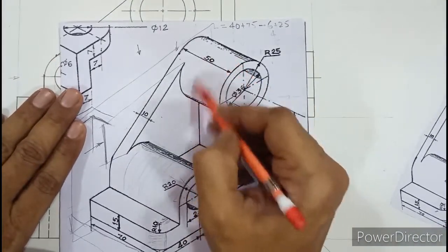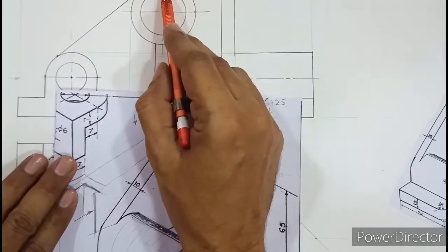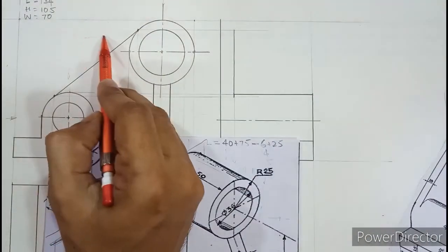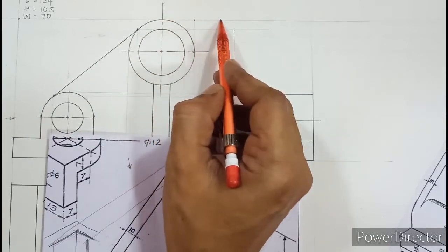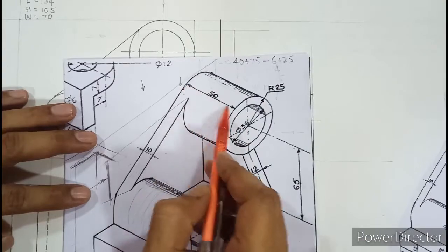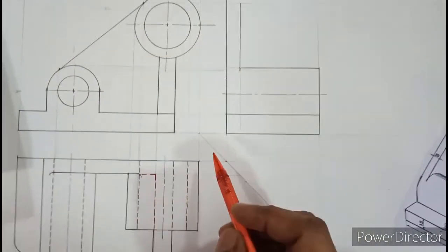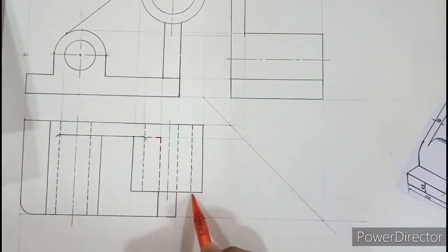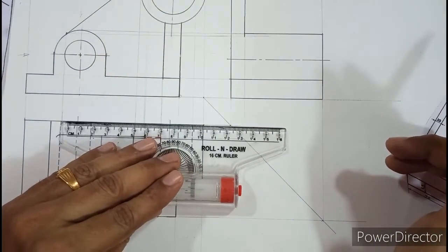The cylinder will also be seen, right? So you can see at the max up to the boundary, and if you look here, this is the boundary. So look at this from the side view. At the max you can see up to the boundary, and the boundary is nothing but the box. But what is the width of this boundary? It is not 70, it is 50. And width you'll always get from the top view. So in the top view, see this is 50, this cylinder is 50. So I need to extend this in the side. Okay, so we will extend this cylinder in the side.